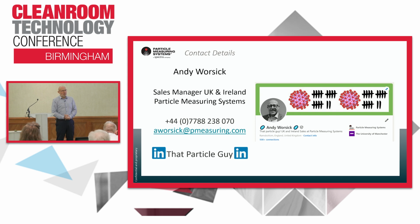But yeah, I think there's an argument there just to do it. I can't say I've seen it done, but I certainly can see where you're coming from. And I think CETA in the US came up with a very good document to identify this point. They said that in primary engineering units like biosafety cabinets or laminar airflow workbenches, the practitioner's area, where the hands are, is the risk zone. Whatever you do, we will consider this location a risk zone. So we will still be within 30 centimeters of this area, but nearby.